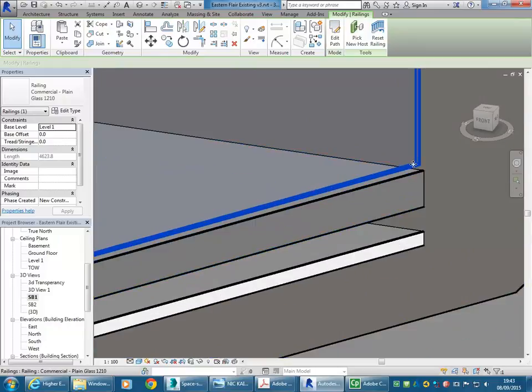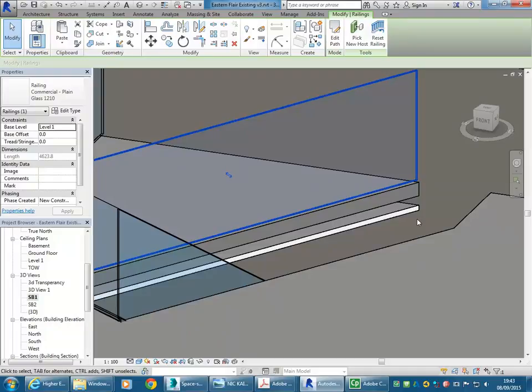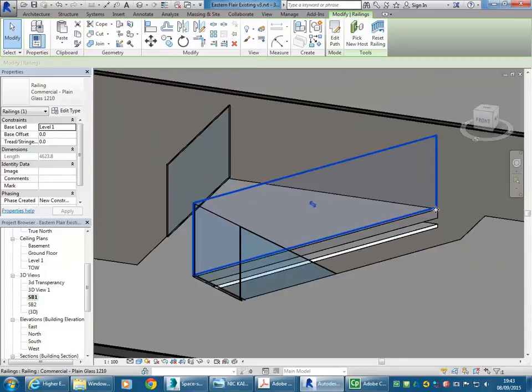So if you're not sure, it's done down in this area that I mentioned before. They'll have the glass extend down past the floor and even the ceiling. Right, so the glass sheet would basically be cantilevering up from that section of floor, and then they would cover that with a steel plate or something, and that would support it. So that's how they do it. And it looks frameless, it looks just like a floating sheet of glass, but it is supported. Oh, they use toughened glass, and yeah, so it's pretty tough.